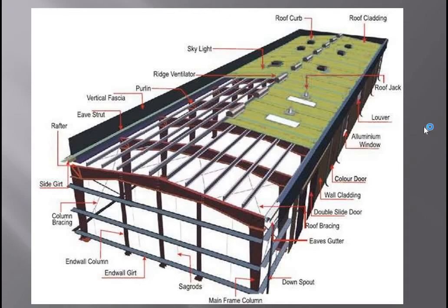So we have to design this. This is the main aim of this course, Structural Design 1. This is the truss, purlins, sheets, either GI sheets or asbestos sheets. Asbestos or AC sheets have become obsolete nowadays because it is a brittle material. It is going to fail or crack. So GI sheets, color coated GI sheets nowadays are very popular. Then side sheeting, side girts, column and base plates.